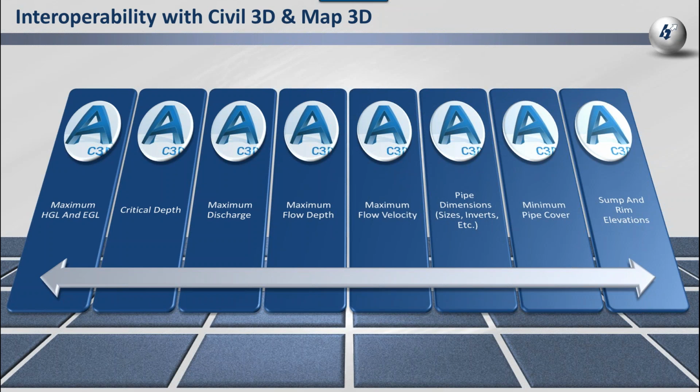Okay, so you can incorporate and change the default settings such as colors and annotations to fit your company's CAD standards. What it also does is it doesn't rely on a style, which we hopefully have all taken on as a challenge to create our own styles, and really kind of lob this back into just plain old basic AutoCAD as far as being able to change colors, line types, etc. by layers, which I always feel is easier to do and much nicer to do in the long run.